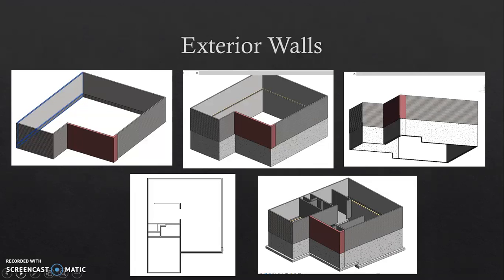Next, I drew in the foundation walls as support for the first floor walls, and here I had to modify the foundation walls because later on I would have the site slope down from the front of the house to the rear of the house. And then I used the generic walls to create the rest on the basement level. And at this point I also added in the footings and the bearings.